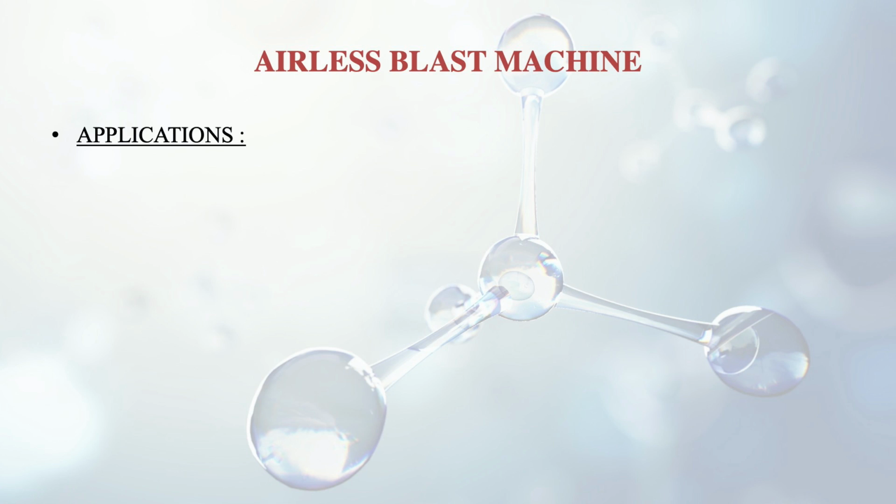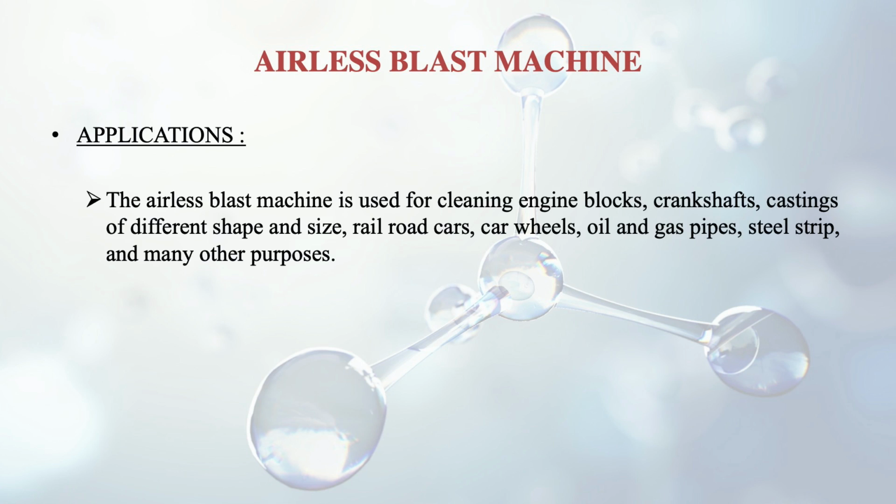And what are the applications of these? The airless blast machine is used for cleaning engine blocks, crankshafts, castings of different sizes and shapes, railroad cars, car wheels, oil and gas pipes, steel structures. So it has many applications because it gives us a very good, excellent surface finish.